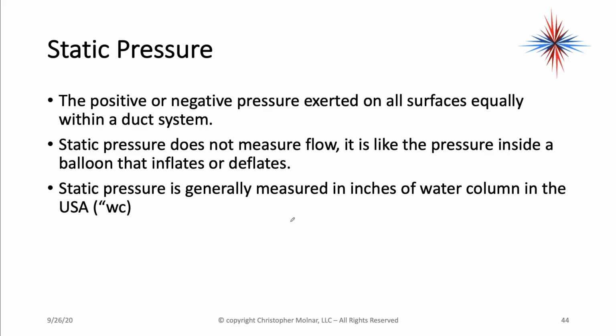Now, we also have some airflow issues we have to look at. Static pressure. It's the positive or negative pressure exerted on all surfaces equally within a duct system. The static pressure does not mean measure flow. It's like the pressure inside a balloon that inflates or deflates. Static pressure is measured in inches of water column in the US.